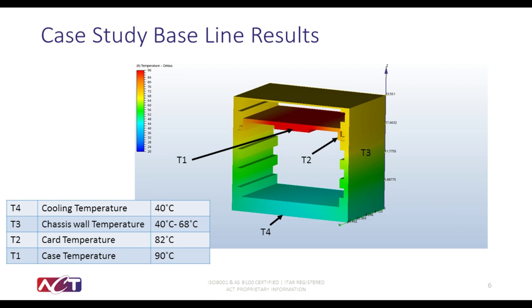The final area we will outline is the spreading along the card frame. If improved heat spreading is needed, copper is always an option. However, it adds weight to your system. As we continue to explore options that don't add weight, we'll look at heat pipes and high K plates.